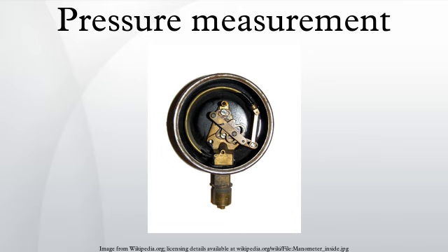In vacuum systems, the units torr, micrometer of mercury, and inch of mercury are most commonly used. Torr and micron usually indicate an absolute pressure, while inHg usually indicates a gauge pressure. Atmospheric pressures are usually stated using kilopascals or atmospheres, except in American meteorology where the hectopascal and millibar are preferred. In American and Canadian engineering, stress is often measured in kip. Note that stress is not a true pressure since it is not scalar.